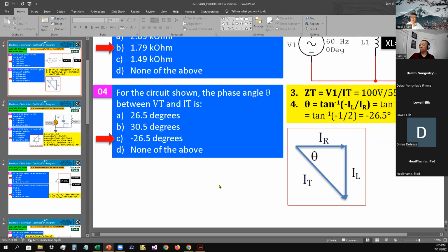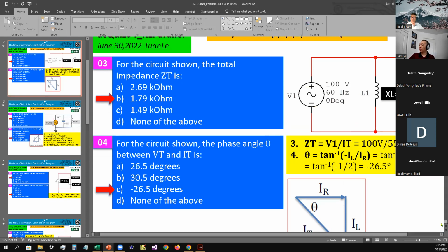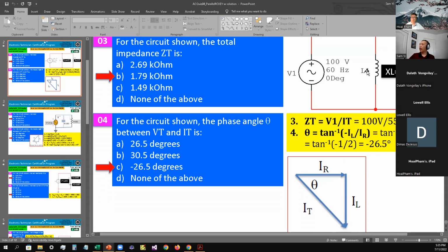Like say if it's negative, then you would have to assume that the direction would have to be pointed in the negative direction. But you also have to remember the concept. The concept is that when you work with an inductor, the voltage leads the current. So the voltage would be going positive toward this side, and current is going toward the negative side.